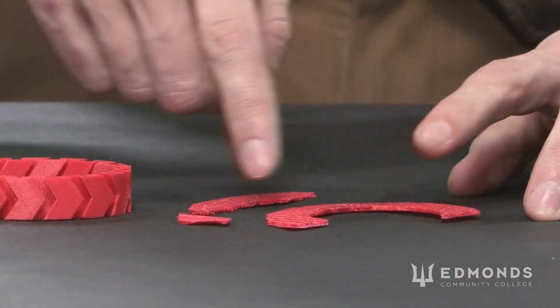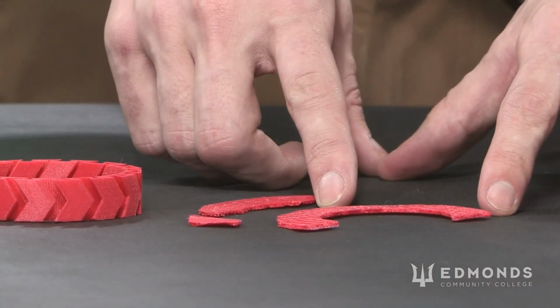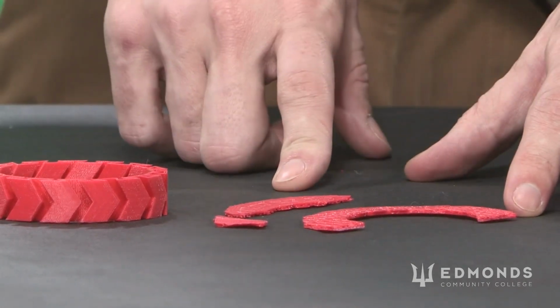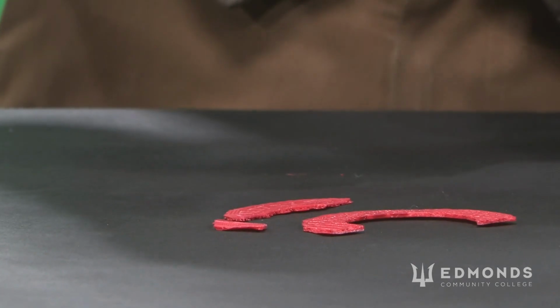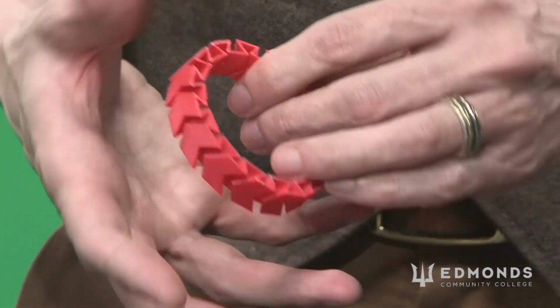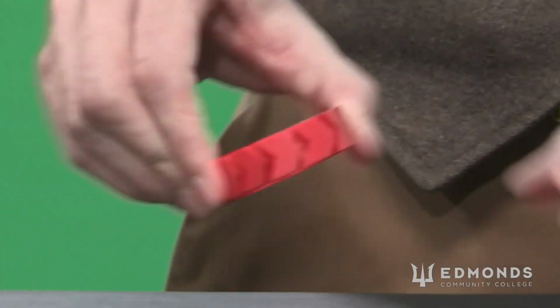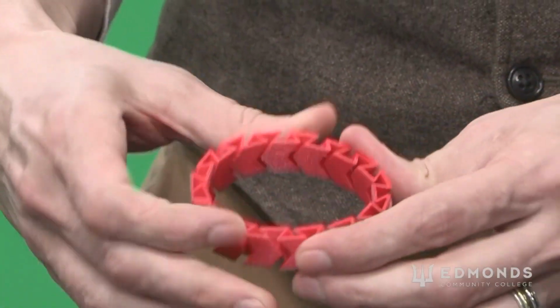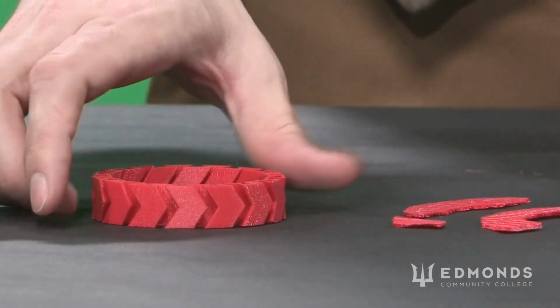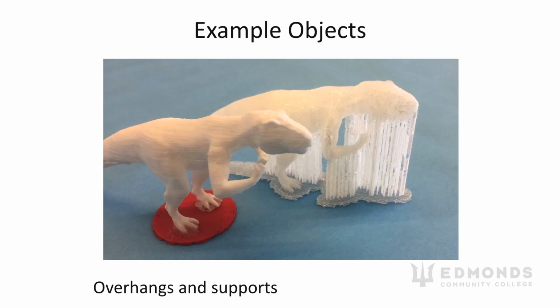And the raft begins with some high surface area threads basically placed down, these layers, these broad threads right there. Whereas then the high resolution layers can occur inside the shape itself. And of course this is also a great example of a shape that's flexible because of its geometry, not because of its material. It's also important for us to be able to minimize errors by producing those supports.